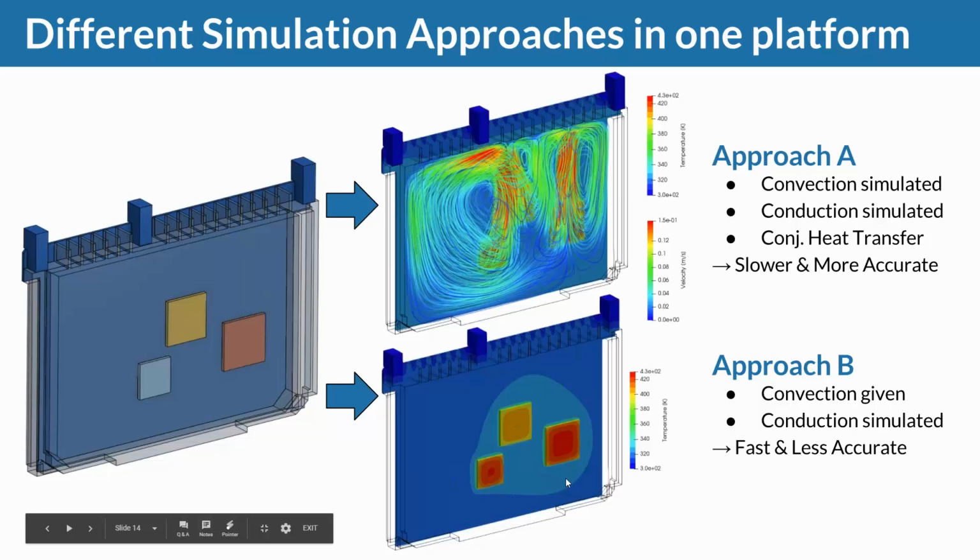So what we're saying is effectively, on these chips, we're assuming the following heat transfer coefficient, and we're assuming the surrounding air to these chips to have the reference temperature of, in this case, 320 Kelvin. And so that's what the simulation is going to do. Whether or not these parameters or these values are accurate or sufficient for your design work or for your engineering work, that's up to you, right?